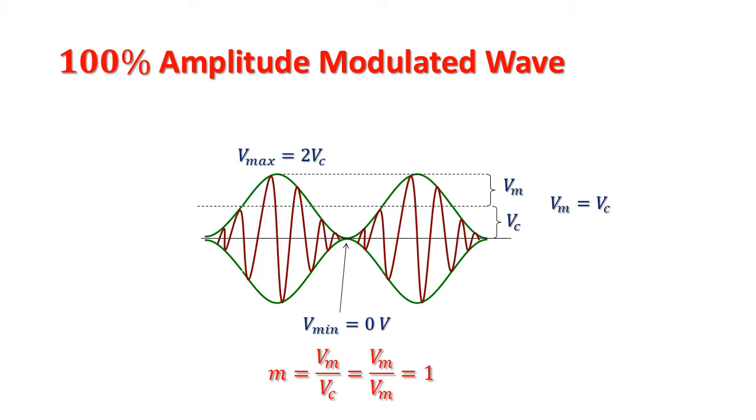In 100% modulation, the carrier is fully modulated and the amplitude of the modulation is equal to half that of the main carrier, that is, the sum of the powers of the sidebands is equal to half that of the carrier. This means that each sideband is just a quarter of the total power. In other words, for a transmitter with a 10-watt carrier, the total sideband power would be 5 watts and each individual sideband would be 2.5 watts.